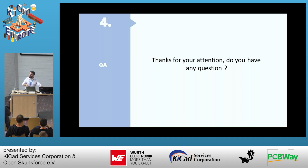We have a web page on our website with all our standard stack-ups. You can select, for example, the copper thickness you want and the number of layers, and then we have the possibility to share with you our standards. However, if you want a specific stack-up, it's also possible, but the price will be different because we have to modify our standards.